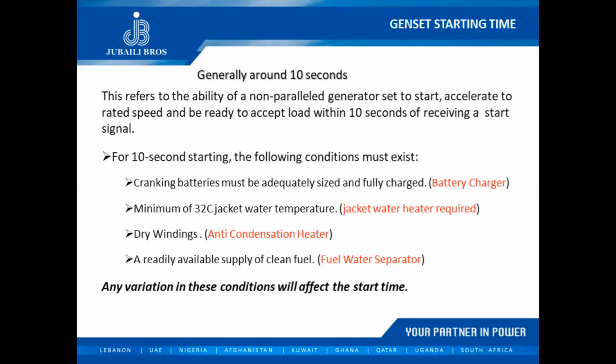And we need a readily available supply of clean fuel, and that's why we add a fuel water separator. In some cold areas, we also recommend oil pad heaters to make sure that the lubrication oil is at the proper density and not clogged in any part of the system.